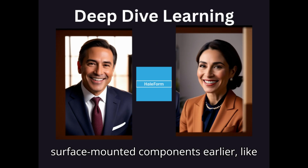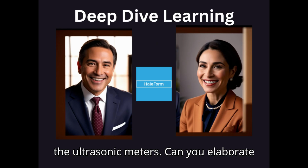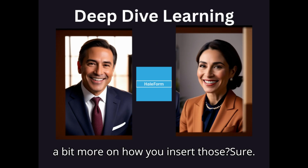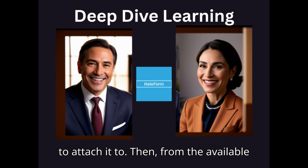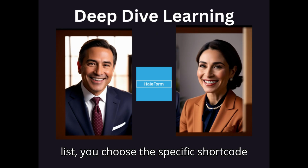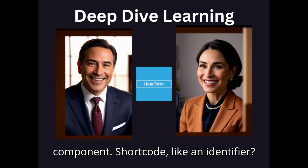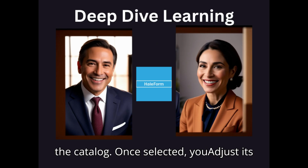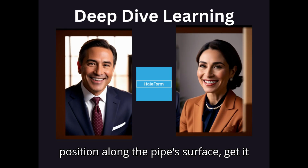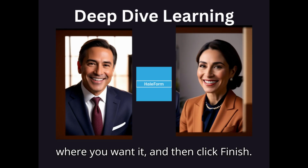Precisely. You mentioned those surface-mounted components earlier, like the ultrasonic meters. Can you elaborate a bit more on how you insert those? Sure. For those, you select the pipe you want to attach it to. Then, from the available list, you choose the specific shortcode and the option for that surface-mounted component. Shortcode, like an identifier. Yeah, it's how they're often defined in the catalog. Once selected, you adjust its position along the pipe's surface, get it where you want it, and then click Finish.